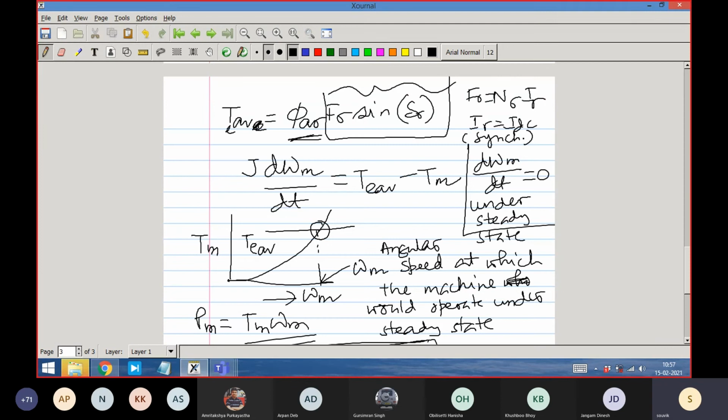Conveyor's speed torque characteristic will decide what has to be the mechanical torque. And therefore, the electrical machine has to develop that torque. So its speed is already decided, its torque is also decided, because speed is decided by the application, and the application and the conveyor belt characteristic have decided the mechanical torque, and that mechanical torque has to be balanced by the electrical torque in steady state. And for the electrical torque, the electrical supply system is already decided. So the flux is decided.